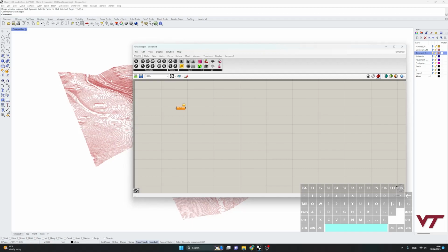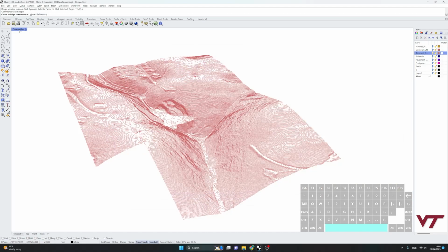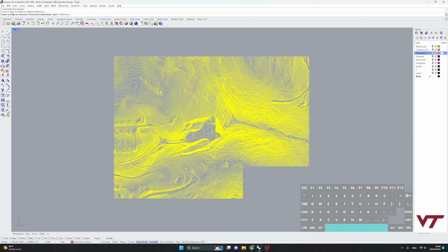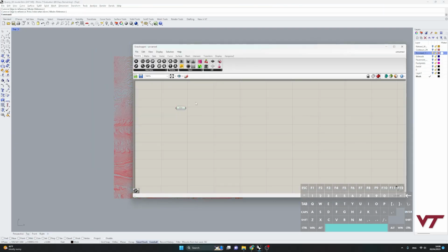While Rhino is a virtual modeling space, Grasshopper is a little bit like a virtual space within a virtual space. Once you get your head around that, it becomes a little bit clearer, but I know it's a little bit odd to think of straight away. Right now, Grasshopper doesn't have any interaction with these lines in here. So the first thing we're going to do with our curve module is link those curves and bring them into the Grasshopper space. We're just going to select all of our curves and hit enter, and that links them in.